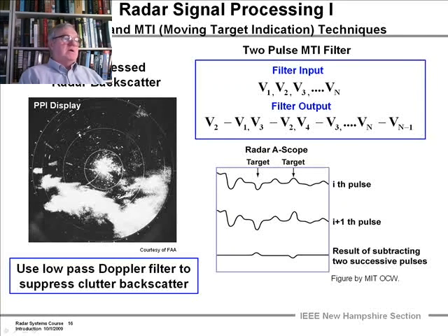These are discrete clutter objects because they don't move. These lines down here are closely spaced towers from high voltage power lines, grids, and they appear like a line target, but they don't move. They're there each and every scan. And what we see here is what rain looks like.